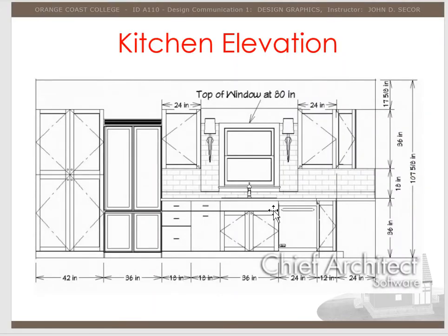Now, kitchens are unique when it comes to elevations because they require a lot of detail, but also most architectural elements are dimensioned in feet and inches, but only in kitchen cabinetry do we dimension only in inches. So this is unique to kitchens only. And sometimes millwork, but mainly that's what kitchens are, millwork. We call this millwork, the cabinetry.